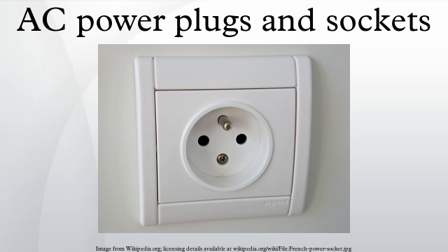Earthing. A third contact for a connection to earth is intended to protect against insulation failure of the connected device. When earth distribution systems became common, earlier unearthed socket types were either replaced with new standards, or revised to include an earthing pin. Different types of plugs are used for different IEC appliance classes. The assigned class depends on whether or not the device is earthed, and the degree of insulation it incorporates. Class I, for example, refers to earthed equipment which requires a third contact in the plug and socket, while Class II refers to unearthed equipment protected by double insulation.